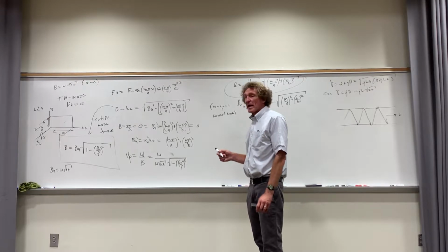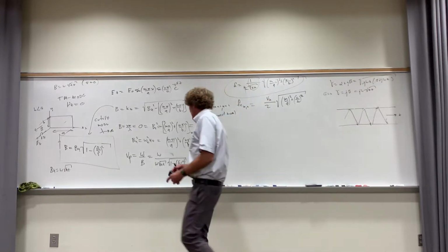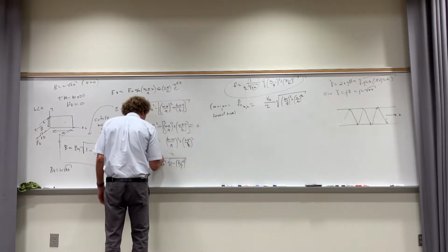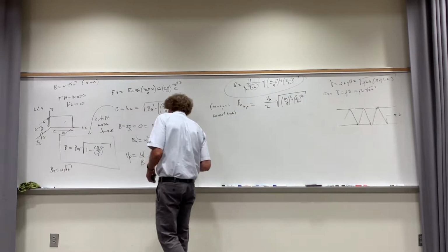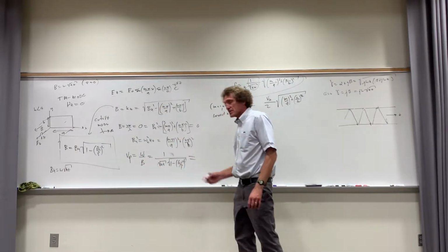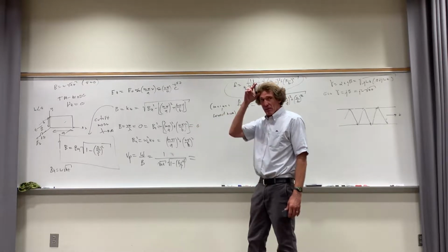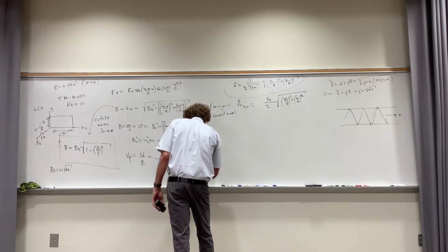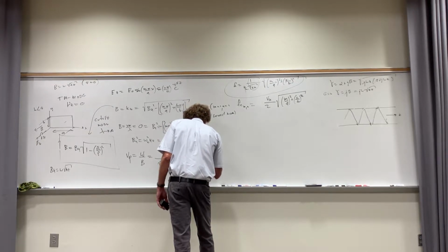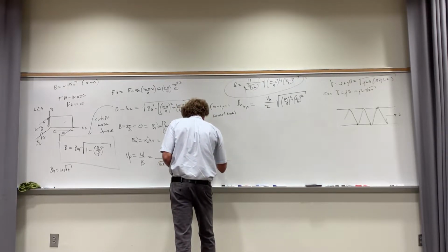Now, you all see how omega cancels? Everybody? So if omega cancels, now I have this. When you see the 1 over square root of mu epsilon, immediately you think velocity of light. I'm going to do one better. It's really equal to the velocity of light, c, over the square root of epsilon relative in the guide. Almost always mu relative is equal to 1.